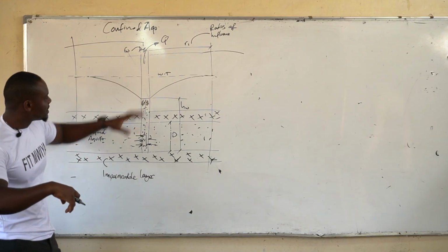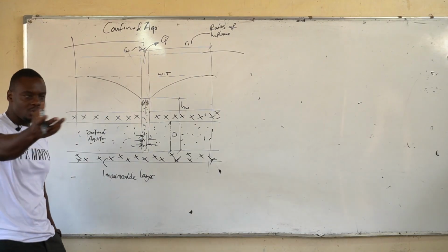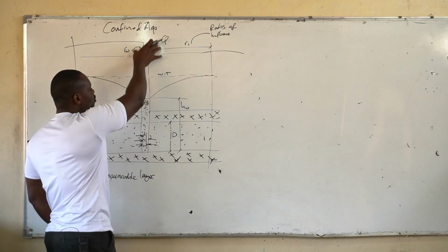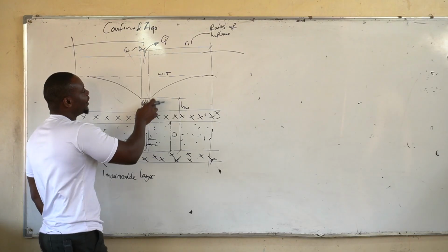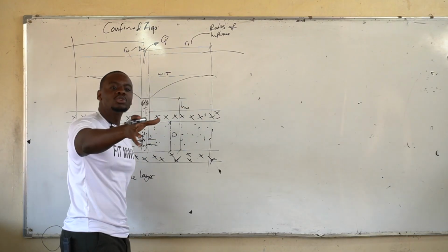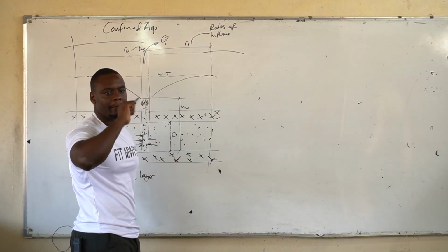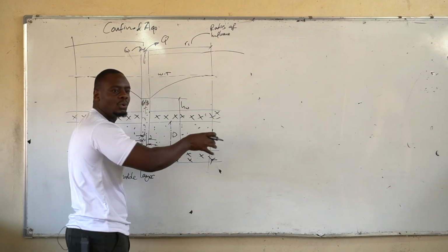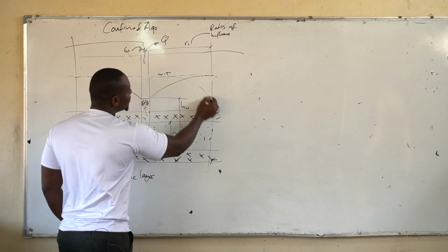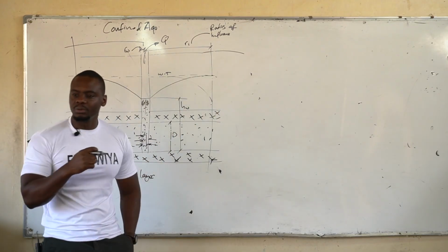And this is very important because we want to know, you as Mr. Maybe Banda, you drew a borehole. No, Mr. Mwale, thank you for that. We want to know how far your borehole is going to affect the next person. Because the next person, again, if they drew a borehole, it's also going to have its own radius of influence.